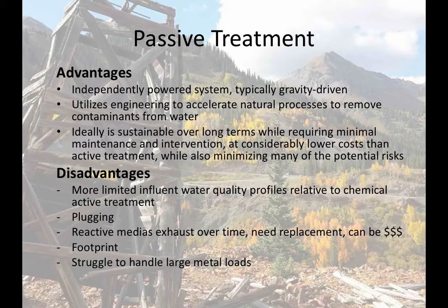But they're pretty finicky systems. You need to figure out exactly which one's going to work for you. Some of them want anoxic influent conditions. Some of them will work better with oxygen in the water, anoxic being no dissolved oxygen present in the water. They've got a pretty specific range of influent concentrations, typically, that the water will even work on. They struggle with some specific analytes. Zinc in particular is kind of a tougher one. And they require a very large footprint.